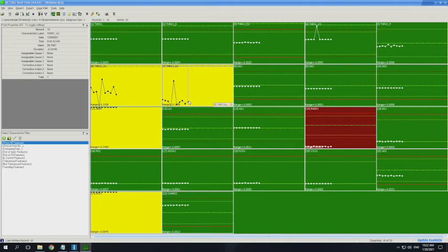So really this is sort of the brains of the operation. The Opticline is a very clever machine on its own, but once you interface it with SPC and data collection, you can start to do truly wonderful things. You can look at drift in tooling, you can set warning limits, you can set notes to operators, you can set it up to view into factories. So if you've got multiple factories, you can actually get a dashboard.